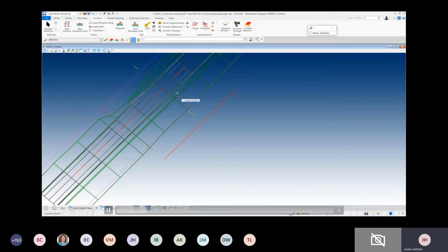Now, if I do this again and basically shut this off and create another key station and snap again to the end of this line, it's going to create obviously another key station at that location and densify the corridor at that location. Now you can see those two marks. You can see the graphical manipulators, but the difference here is this one is a persistent snap, and this one is not. Meaning this is ruled, and this one isn't.